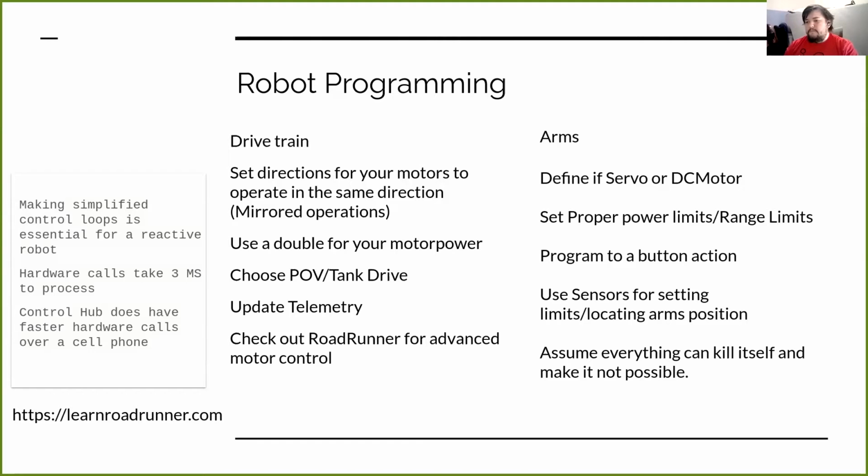lag. I think most of us probably have played a computer game, right, where it's multiplayer or even like Minecraft. If you have 250 millisecond lag, it's noticeable, right? Like, oof, that's a hard ping. So keep that in mind when you're designing your robot with your control loops. You want to try and keep those sub 100 milliseconds or even less. That'll translate to real world performance in terms of how quickly your robot will respond to things.